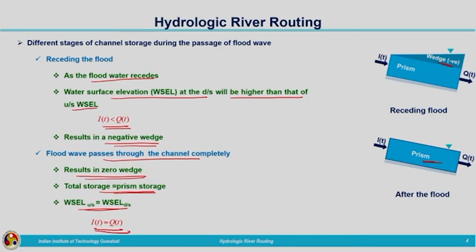So, in between these stages, flood wave is entering the channel, it is moving away from the downstream location where the flow details have to be calculated. We need to get the Q value or the flow characteristics at the downstream location based on the known flow characteristics at the upstream location as the flood wave traverses from upstream to downstream.